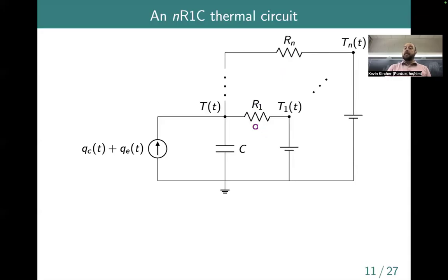Yes. Sometimes that can be done directly by thinking about the thermal properties of the materials. For example, if we were thinking about conduction through that wall, you can think about what it is made out of. Cinder block. What is the conductivity of cinder block? And you can go from there to getting at least an estimate of R. It would have to do with the thickness of the wall as well, things like that. That's one way to do it.